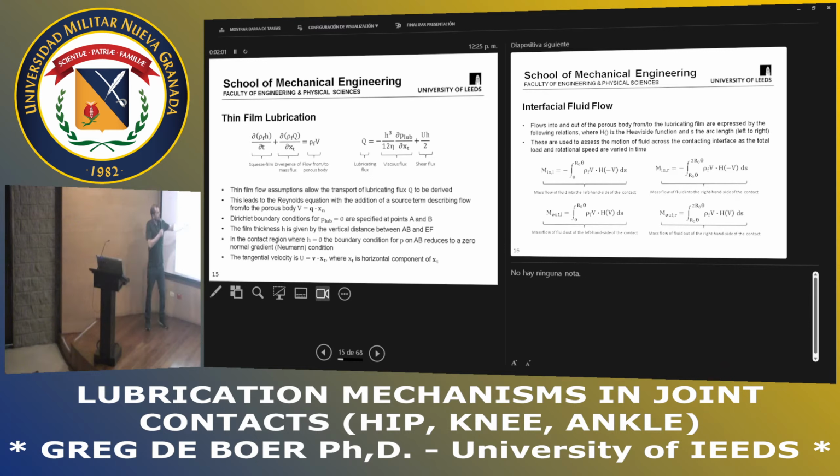These two terms here, again, the left-hand side of the equation, is what we could call classic lubrication theory. Okay, so lubrication theory takes a fluid flow equation, Stokes flow, for example, and then assumes through that very thin film that everything is constant, and then we integrate those equations over that film, and we can obtain this equation. This is known as Reynolds equation without this thing on the right, and that is the same Reynolds as your Reynolds number, but a very different application.